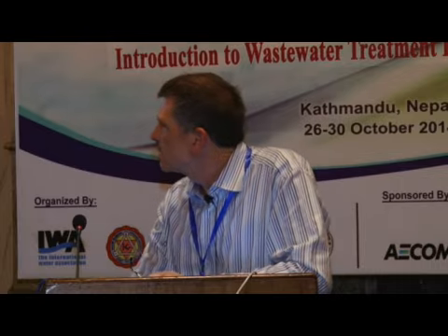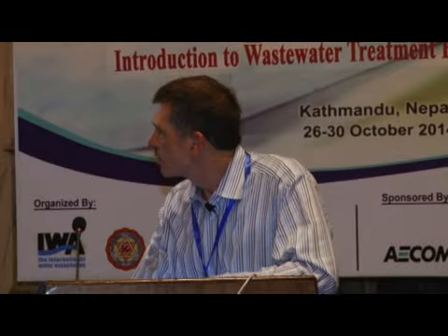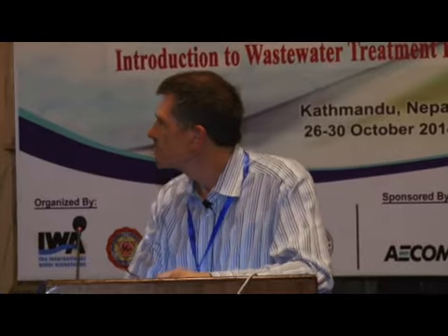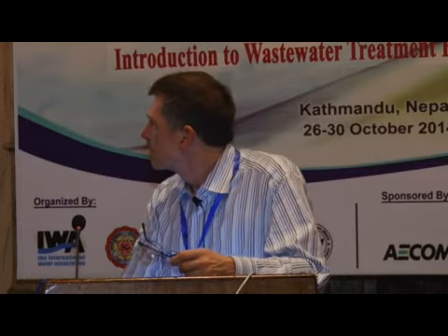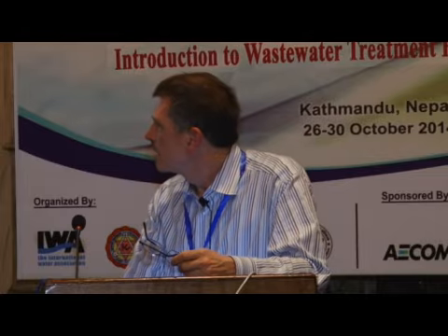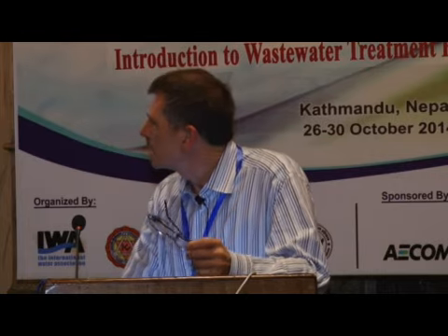So we see our COD, which is of course really high in the reactors because you have sludge in there. You measure total COD, so it's not an important number, but effluent is 35 COD. TSS is 10 because of the simple model. VSS 7.6 in the effluent. And then there is that zero DO that I think Karthik explained in the influent, and 2 milligrams of DO in all the reactors, the diffusers, because there is a high oxygen uptake rate. You see that here it's 73 milligrams of oxygen per.